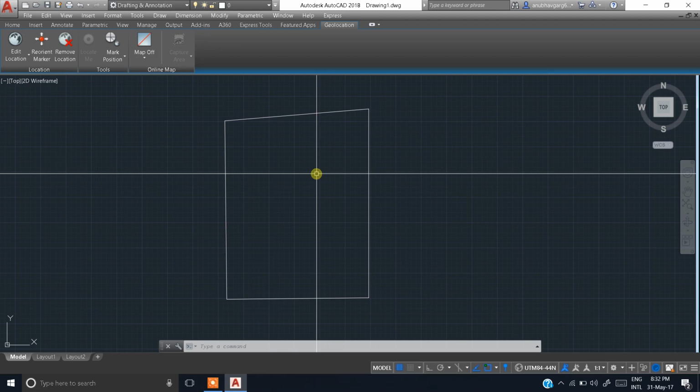Okay, and I personally prefer to give the setback, because if you close all three sides of the building, then there is no more space left for the air to move. And what happens if the plot or the land next to you also creates a building, and he also doesn't leave any offset at the perimeter of his building, then it becomes really congested for the people living in that building. So it's my personal preference that you should leave a minimum of 750 of space. Okay, 750 is roughly around 2.5 feet.